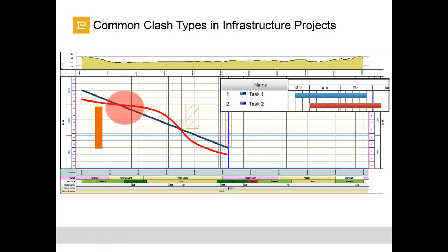So of course these conflicts should be analyzed to see if they are really conflicts, if these two crews can work together or not, and we should also solve this problem. This is also a unique feature of TILOS. We can add lags, but not only using time. So for example, here we can say that between 2 tasks we are going to have a 10 day lag before the second activity can start. But in TILOS, we can also give a distance lag. What does it mean?